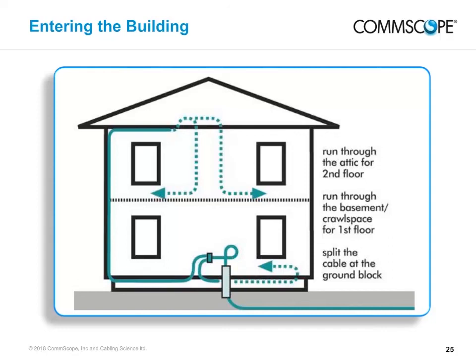Try to follow the architectural lines of the house and run the cable in places where the foundation meets the bottom of the exterior walls or vertically along the corner trim or under the soffit. You can bury cable next to the foundation, keeping in mind the burial depth per NEC 820. Avoid placing cable in direct sunlight, as that will accelerate cable aging. Consider a non-metallic raceway to hide and protect the exterior cable.